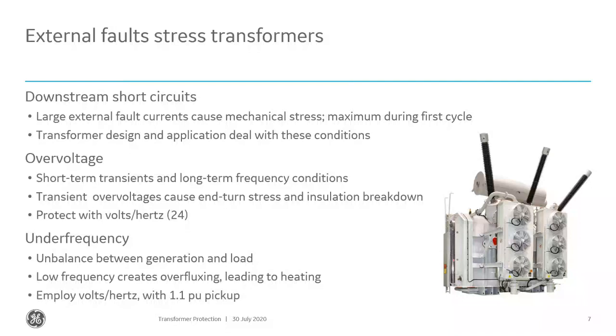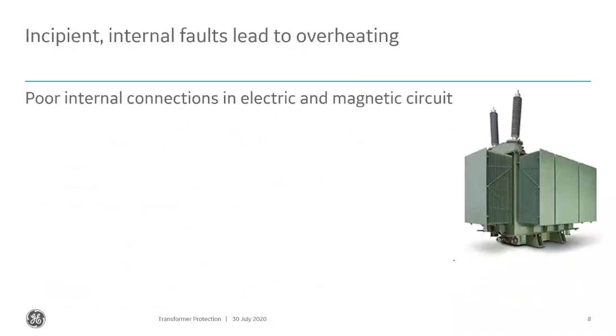There are some incipient faults that could cause us some problems as well. A lot of these are related to heat or other mechanical issues. So if we lose the fans or the pumps, or we've got blocked cooling, right? The radiators are blocked by dirt or debris or leaves or who knows what else. We probably want to trip our alarm from that.